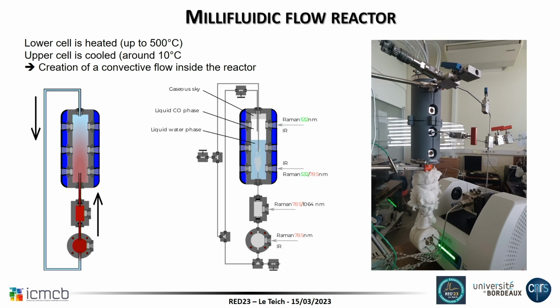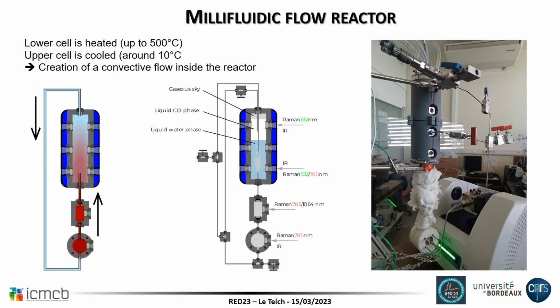Interestingly, when you heat this and cool this down, heat this up, cool this down, you have a natural recirculation that occurs. Exactly what happens in the hydrothermal pump that I mentioned just before. You just have to maintain the temperature gradient from here to here to have a recirculation of the fluid from hot to cold, and then back, if you close the loop here.